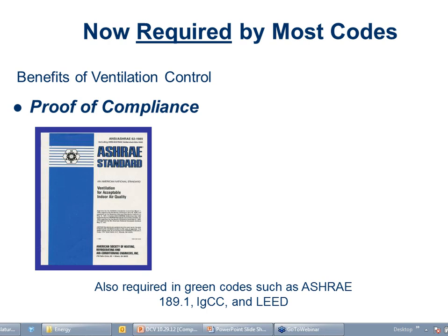So, for example, if I have a conference room that's surrounded by 10 private offices, and everybody's sitting in their private offices doing their thing, and I'm ventilating based on the return air, and everybody's happy, if everybody gets up out of their offices and goes into the conference room for a meeting, which is going to happen every day, right? Now there's nobody in the perimeter offices, and everybody's in one single zone. The return air CO2 sensor is going to read the exact same amount because I still got 10 people returning air back to the air handler, but they're all in a different room. So the damper for that zone is not going to be able to bring enough air into that room on its own unless I know that they're all in that room. So on a VAV system or any dampered system, I have to track the CO2 to the zone level. It's the only way to do it.